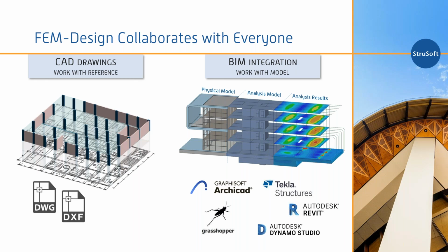And then you have the BIM integration with software like Revit and Tekla, where you take the analytical model from this BIM software. You import it to FEM-Design, and then you work directly on the analytical model. Get results and, of course, design if necessary. I would like to point out that it is very important that the analytical model, even in the BIM software, in Revit, for example, is consistent.